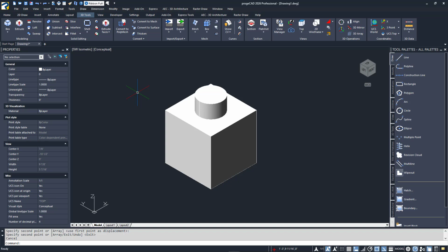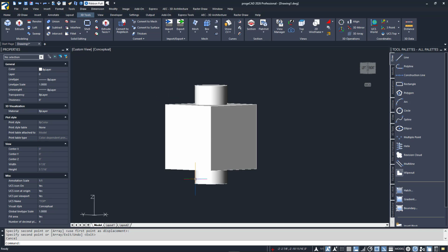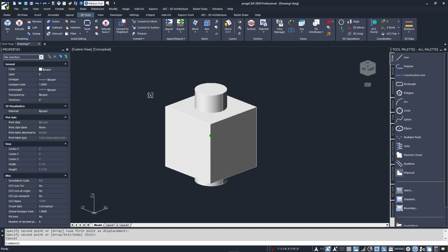For the next tool, I'm going to bring in another box and cylinder, but this time the cylinder crosses through both the top and bottom planes of the box. This tool is called Subtract, and is certainly the most common method to make holes, which is what we want to do. In other words, I want to subtract the cylinder from the box. I'll launch the Subtract command.